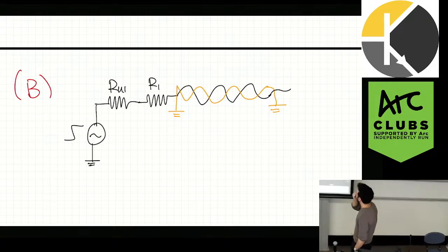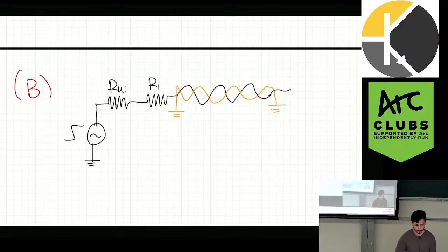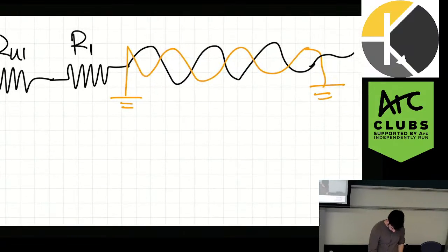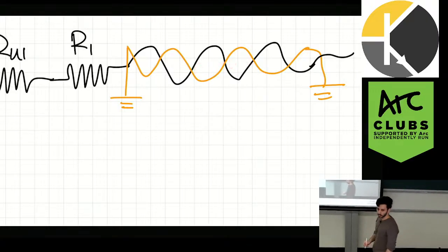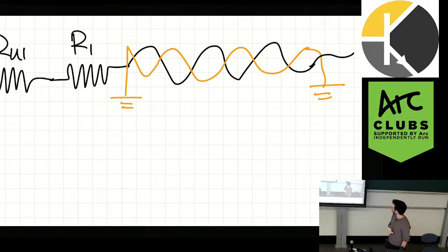The reason we twist the lines like this is for better transfer of data without too much magnetic interference. When you coil them, you have a magnetic field that coils one way, but then one that cancels the other way, so adjacent magnetic fields cancel each other. I don't know if that's content, but it helps with magnetic interference. It's also to make sure that both signals pick up similar noise, so that when we compare them against a reference, because the noise is on both of them, there's no problem.